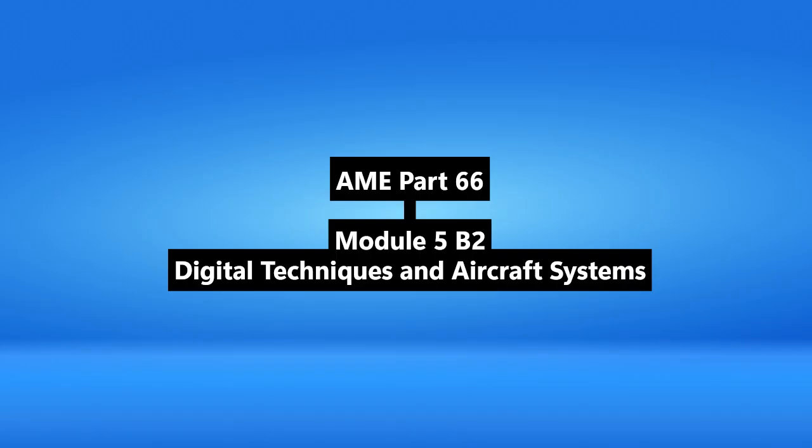Right. And then going the other way, when the computer needs to, say, move a control surface or drive a gauge, that's the job of the digital to analog converter, the DAC. It does the reverse. It takes that sequence of digital numbers from the computer and reconstructs an analog signal from them. It often works by generating tiny impulses based on the digital values, and then those impulses are smoothed out by a filter to create a continuous-looking analog output.